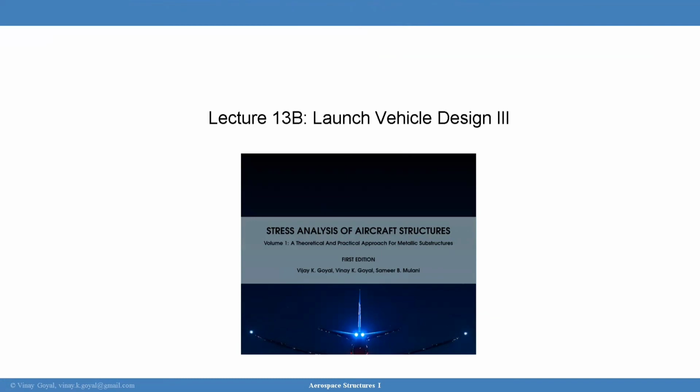You want to make sure that for the launch vehicle design, you get the loads validated through wind tunnel testing and scale that up, and then really understand the dynamics. The dynamics then drives the structural loads, which are then verified through component level testing and also analyzed further to make sure you're protected against the A basis and the 99.90 loads.